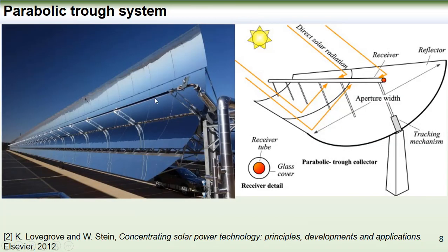A parabolic trough system consists of a field of rows, each row with a parabolic trough shaped mirror or mirrors with a tube along its linear parabola focal line. The mirrors and the tube are mounted on a system which tracks the sun on one axis from east to west. Within the tube, a synthetic oil collects the solar radiation in the form of thermal energy.